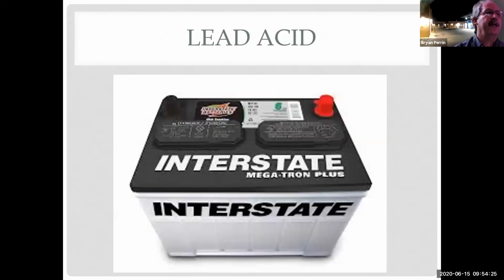So here is a standard lead acid battery. We can see on the top here, I have 2 caps. And so if I pop these caps off, I would see 6 cells. Each cell generates 2.1 volts for a total of 12.6 volts. So my 12 volt battery is really not a 12 volt battery. It's a 12.6 volt battery.